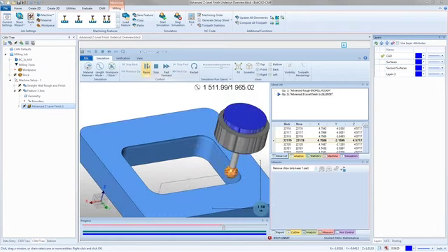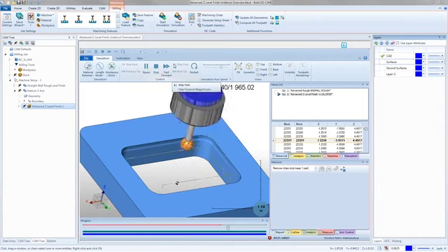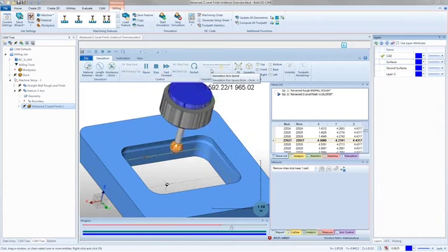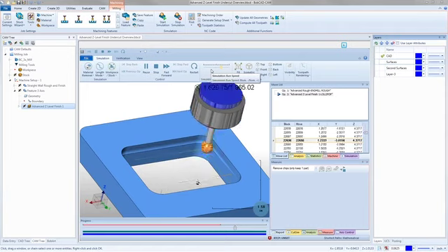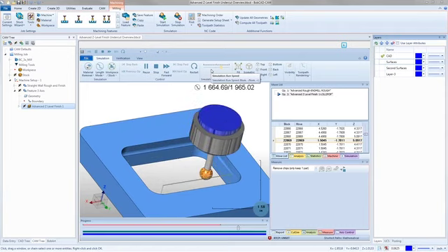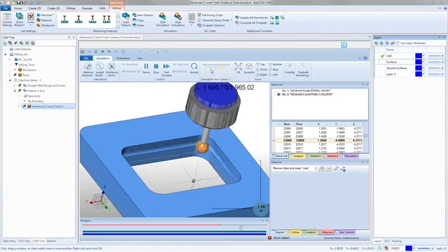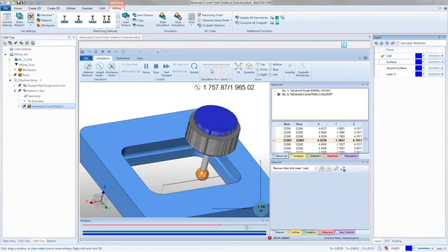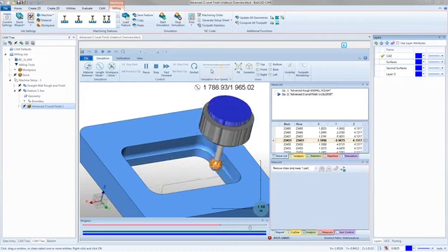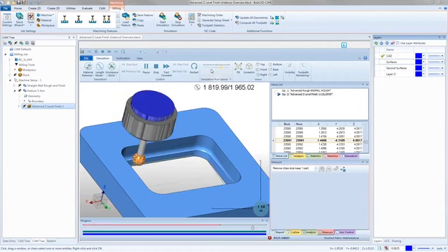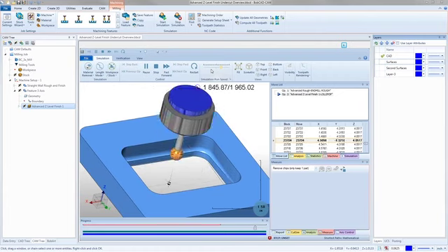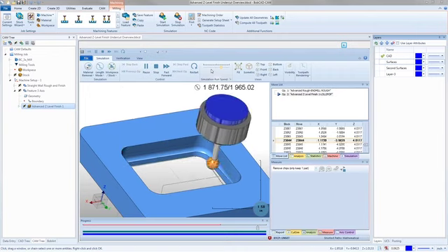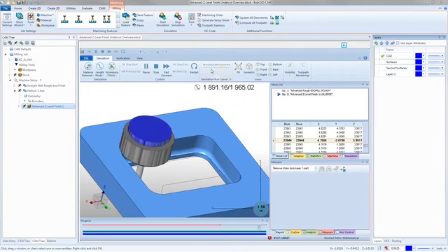And so the tool is going to cut its way in, and it's just going to slowly start putting that taper on. Now, I think this is about 20 thousandths for the depth of cut, and it's a decent finish. The problem that we run into with it is, as we start to get closer to the bottom, the tip of the tool, when it hits either, let's call it the bottom of the stock or the bottom of the part, it stops cutting. It's kind of done at that point. And so that's what we're going to see here in a second.